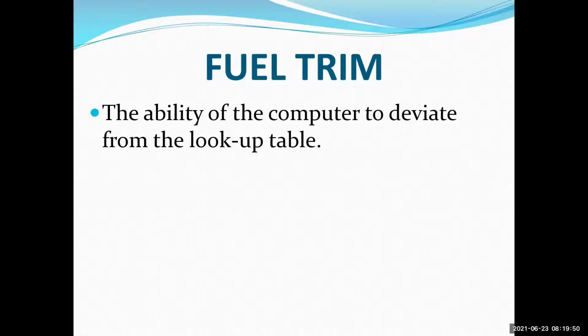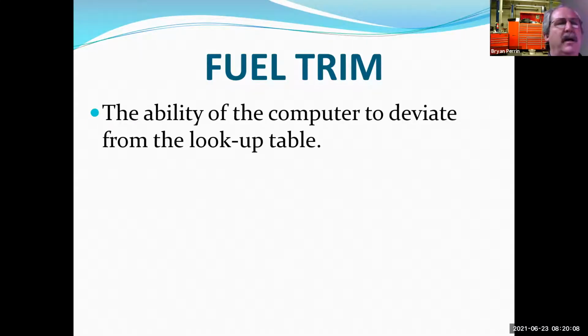But how would we know that if the sensor is showing no problem because it's reading the averages of the cylinders? How would we know to check each and every one? Because there is another code that is showing a problem. Yeah. So in the case I was talking of, I had an issue where I had excessive tailpipe emissions. That's what led the customer to my door.